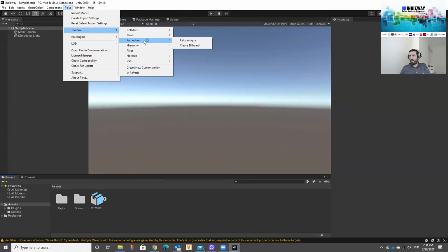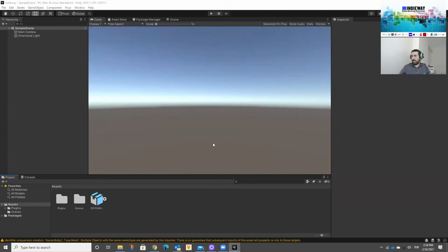For example, you have a wheel, a driving wheel, and there are cards around it, but in the middle there is an engraved logo. And if you do decimation, I mean, if you try to optimize the mesh, of course, the program will not understand whether it's a logo or not. So it will be ruined. Therefore, you will subject them to topology once again to increase the number of meshes at certain points.